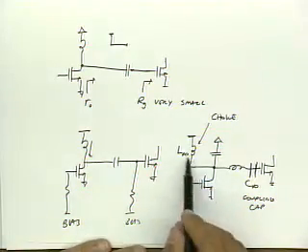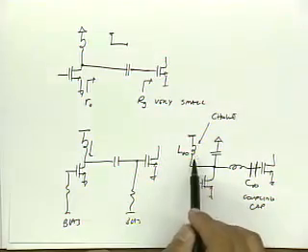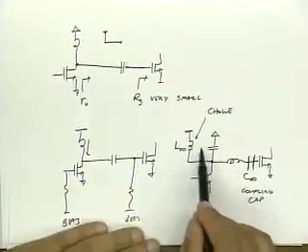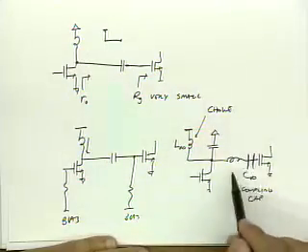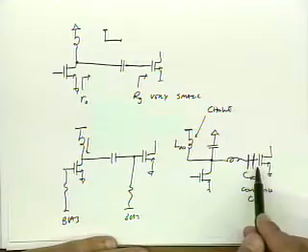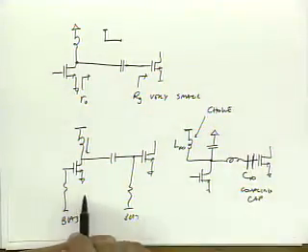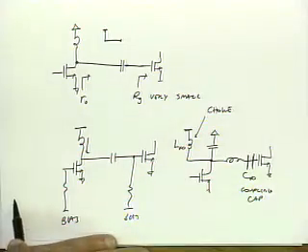And in practice, basically any large inductor acts like a choke, it basically doesn't upset the AC operating point because at RF frequencies it looks like a high impedance, and so it kind of disappears. Same with a capacitor. If I put a capacitor in series that's very large, at high frequency it looks like a short, so it doesn't upset anything, but it does prevent the DC operating point of this stage from interfering with the DC operating point of this stage.